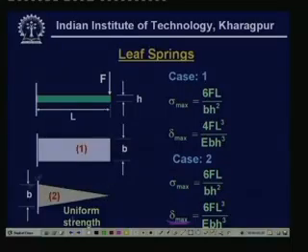So, a non-uniform cross section gives you uniform strength, lesser material and more resilience. In one way this is a better design in comparison to uniform width beams. So, in leaf spring design, people normally choose this type of uniform strength situations.